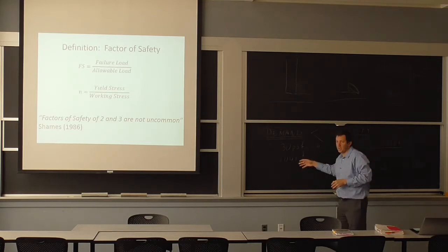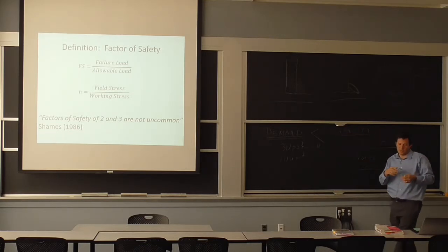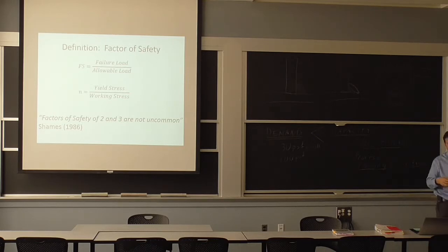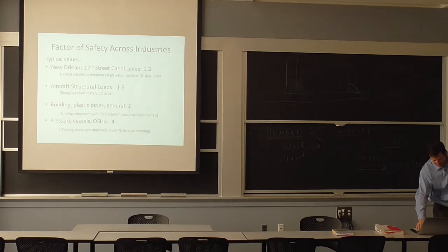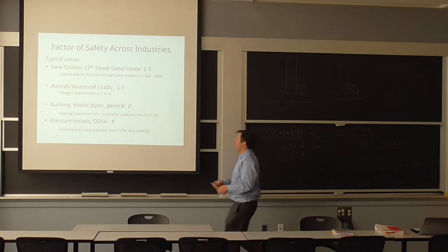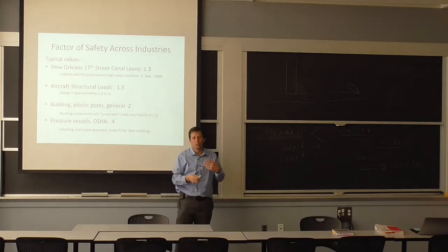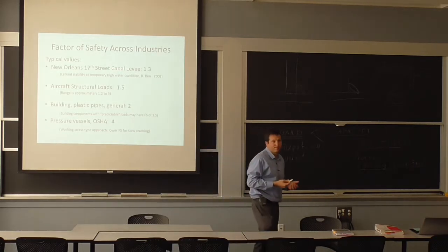Instead of calculating it here, they just say, you know what, if this is a line for a certain pressure, I want a factor of 4 over that pressure against the yield strength. When they go to the yield strength in ASME, typically they will be using a minimum. They won't be using just a typical value. So they'll go from the manufacturing specs. So the reason why in ASME specs, piping system, the safety factor looks really high is because they don't go through all the scenarios of the demand.